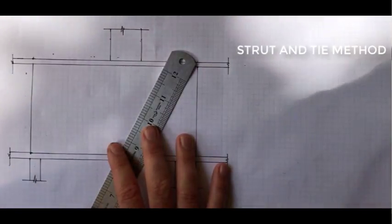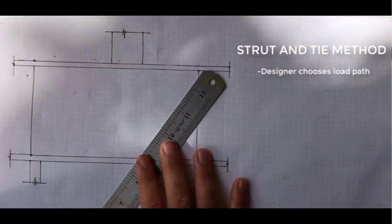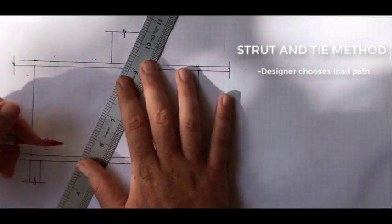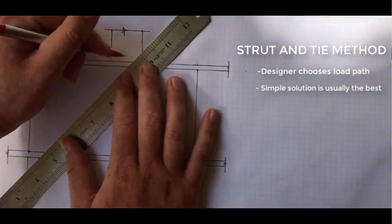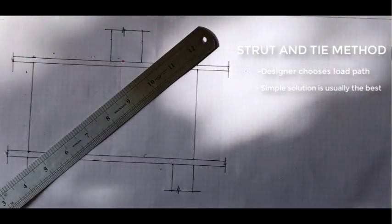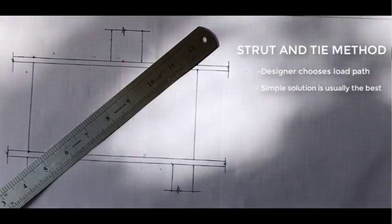With the strut and tie method, you as the designer get to choose the load path, but usually the simplest option is the best. Right now we could potentially make a really complicated truss system, but you're best off just choosing the simplest. So what we're going to do is say the load starts here. And one important thing as the designer is to choose where the nodes are. Where the nodes are is where you're going to put the reinforcement.